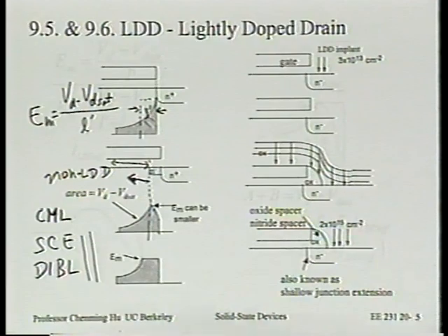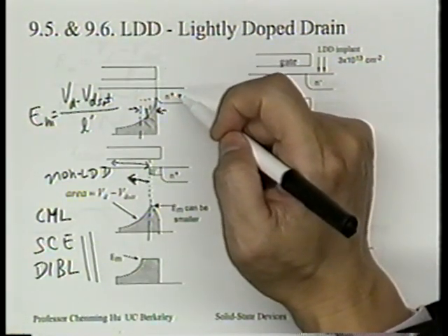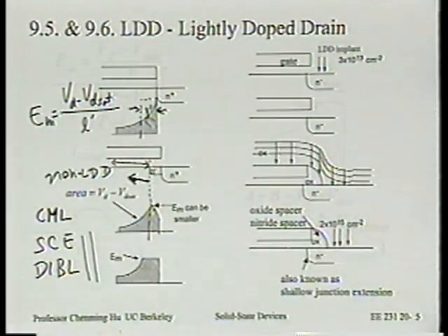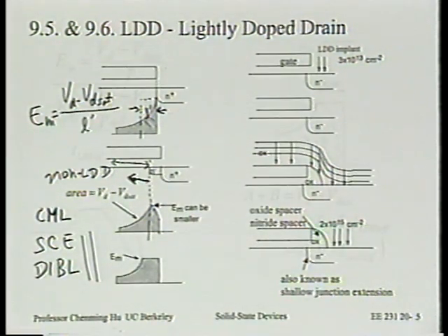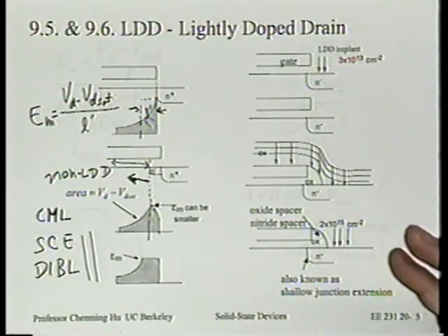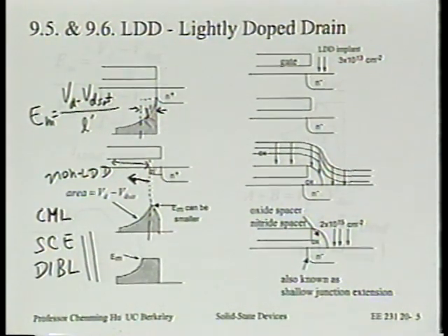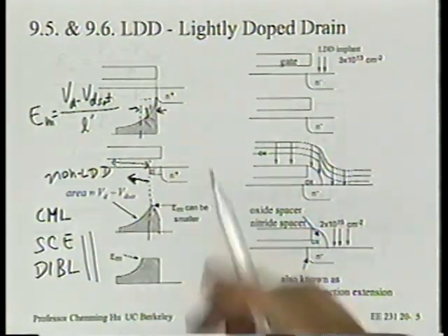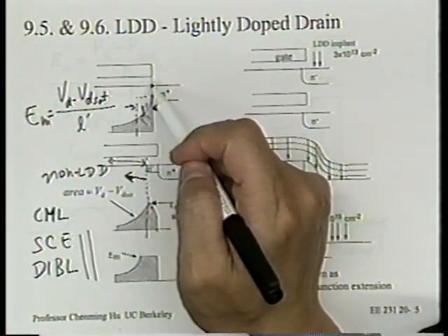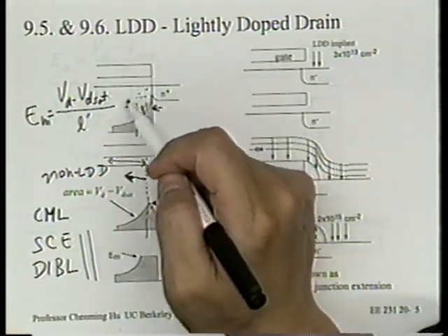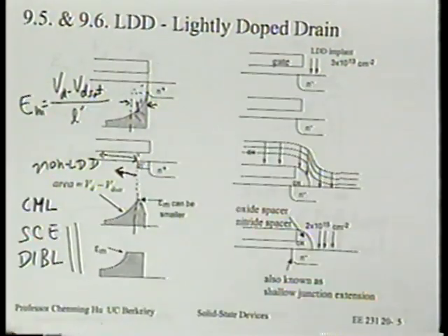The fact is that all the device design tricks we know of so far before we reach LDD, namely doping concentration and junction depths and oxide thickness, or retrograde doping surface layer thickness, everything we can think of, really qualitatively is affecting one thing, that is how long or how short a distance does it take for the electric field to die out, coming from the drain and die out as we move into the channel.